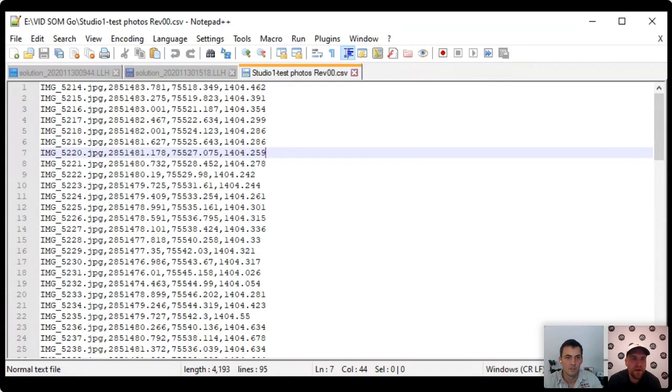You get a text file, and this one can easily be imported into 3D survey. Yes, guys, exactly that. You get a normal CSV data set, which you can import and use as your new telemetry instead of using your old telemetry on your device or your phone that you have used to take your pictures and do your survey. You have all the relevant information in here: image name, X, Y, and Z coordinates. This is exactly what we need in order to get a good 3D model.